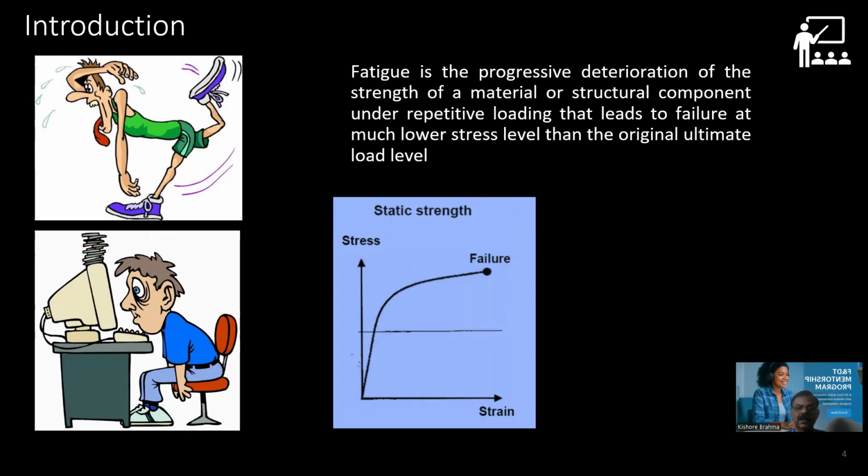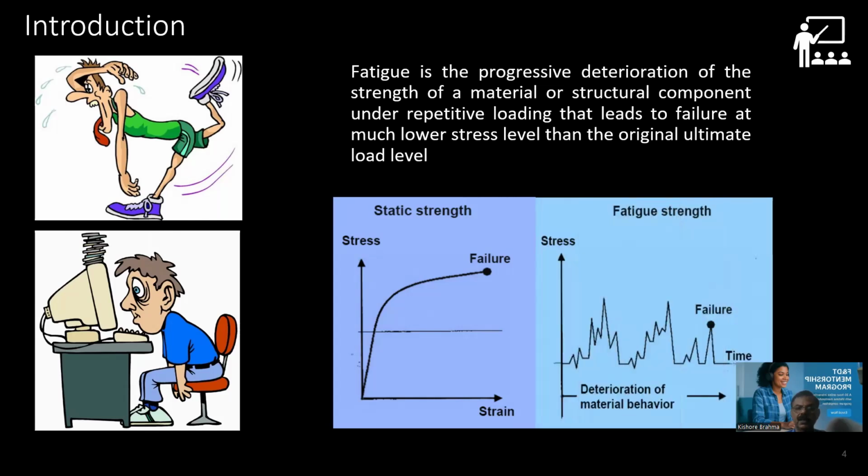To understand its significance, when a structure is subjected to a uniaxial, slowly applied tensile load, the failure will occur in one cycle once it reaches the ultimate strength. But in fatigue, though the loads are very small, the mechanical degradation starts from day one, from the first cycle, and it starts inducing damage which is not recoverable like in human beings. With every repeated cycle, it accumulates the damage, and finally it reaches a critical condition where, with a small load, it leads to catastrophic failure.